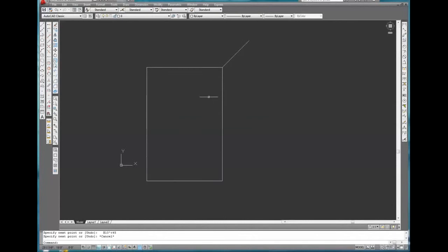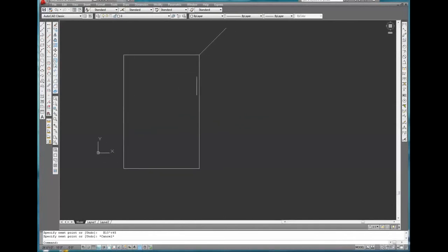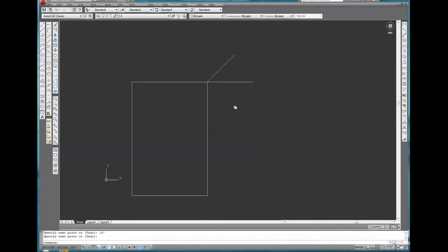So that's a second way of entering in a line, and that's going to be your best bet for when you want to draw angled lines. Otherwise, you're better off just turning the ortho on and just starting a line, pulling it out a ways, type in a measurement, 12 foot, enter, and then enter again to set it. That's the simplest way to do a line.